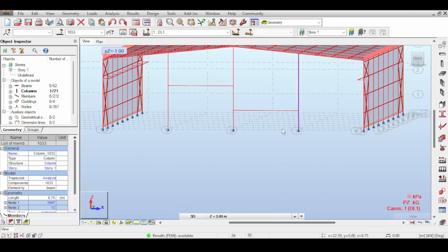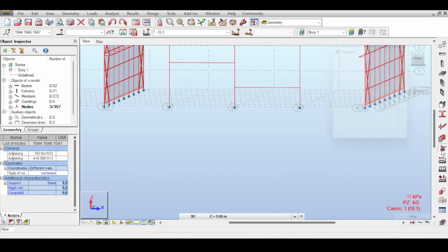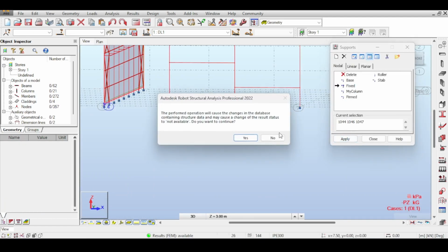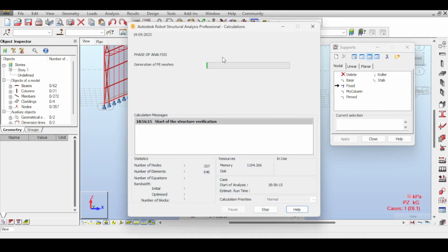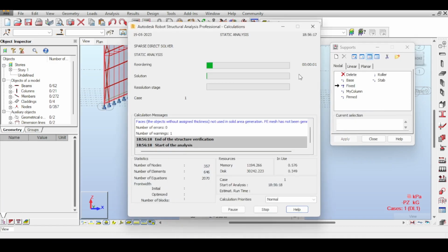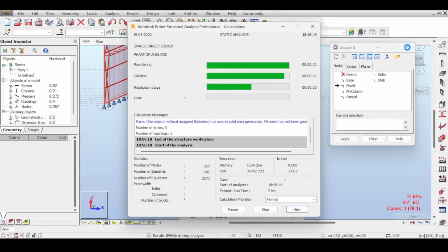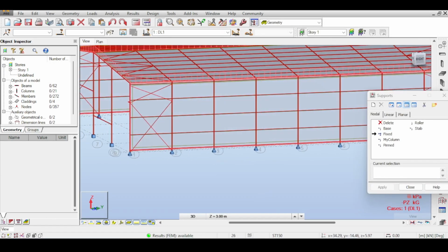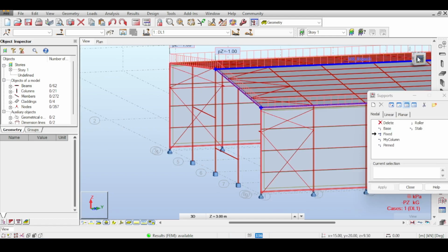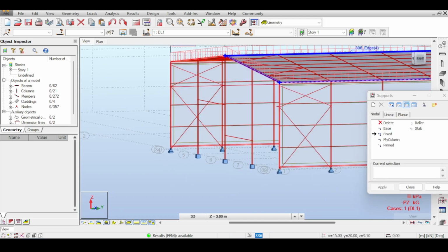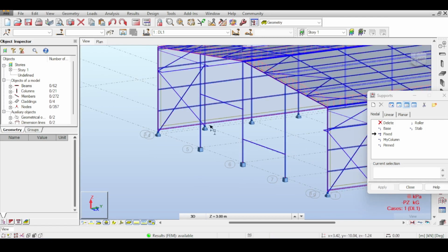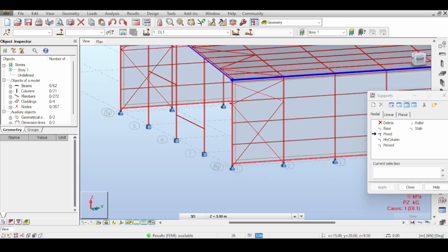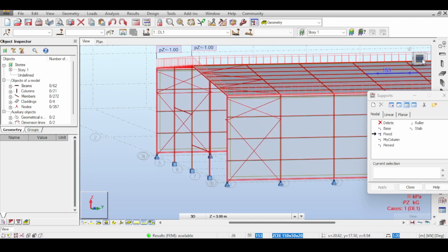Now, I could, of course, fix all the supports here. This would fix the problem, by the way. Now the supports are fixed, and you don't have any instability. So you think you're perfect, you think you are happy now, but I am unhappy. I know a fixed support here would help solve my stability issue, but I have a problem with the fixed support itself, because something that you should do, and I will not do it today, is to provide purlins, and those purlins would have cladding, so the entire wind load blowing on the side is going to be resisted by the gable frame.